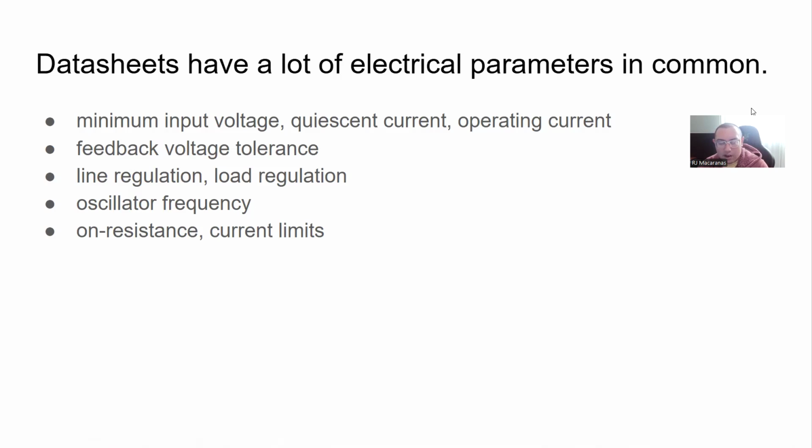And then we have the on resistance. This is specific to MOSFETs, or any kind of transistor really, but MOSFETs specifically have what's usually called RDS(on), the drain to source on resistance. When the MOSFET is conducting, current is flowing from the drain to the source, and that path has some amount of finite resistance. Ideally it would be zero, but of course there's some resistance, and that resistance will lead to copper loss or conduction loss.